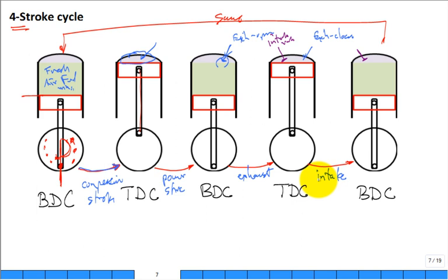It's a cycle. It just continuously repeats, right? How many people ever got on the highway and they look, they have a tachometer, their engine's running at 2,000 RPM. You know how many times that cycle is being repeated? That's a very, very fast operation, going again and again and again, okay? We should make that calculation, but not right now, okay? But so here I just started with the compression stroke, and then the power, then the exhaust, then the intake.